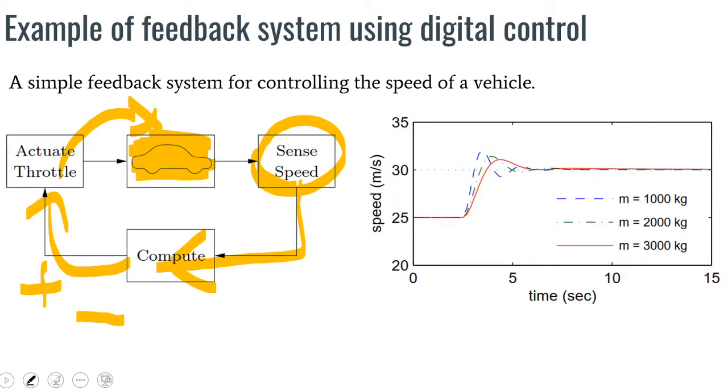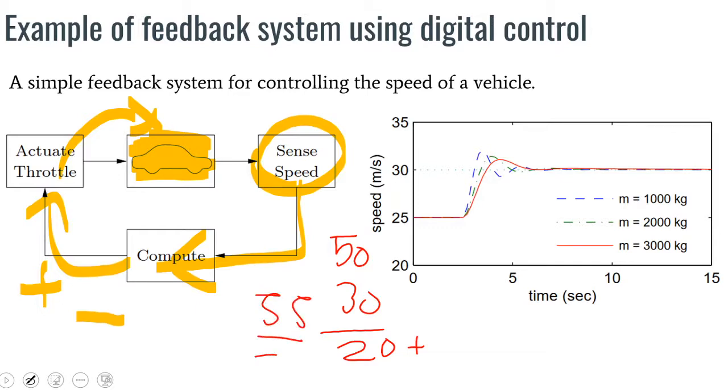That is the basic idea again of how we would use these control systems. Let's say we want to achieve 50 kilometers per hour, and what we are detecting is 30. So we still need another 20 change. But if we achieve 55, then we need to reduce the speed by 5. So we can keep making changes based on what the output is sensing at the end.